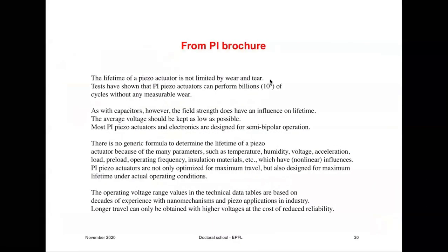You can see many considerations that you have to take into account when using piezoelectric actuators here. And I will not go into too many details here. There is no one rule how to predict the lifetime of the actuator, because this depends on the temperature at which you use it, whether you are always applying the maximum field that you can apply or lower fields. It depends on the frequency at which you use it and so on.